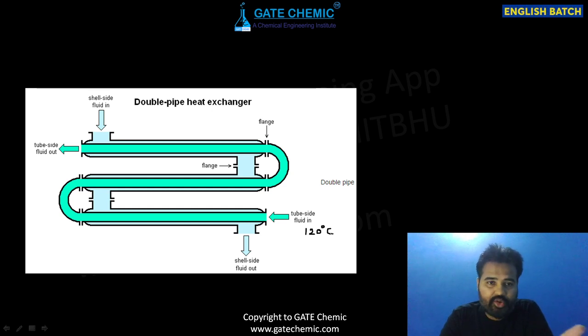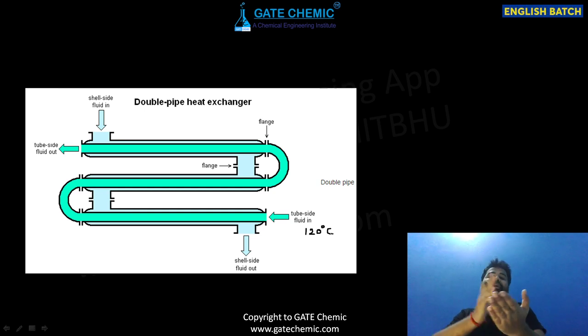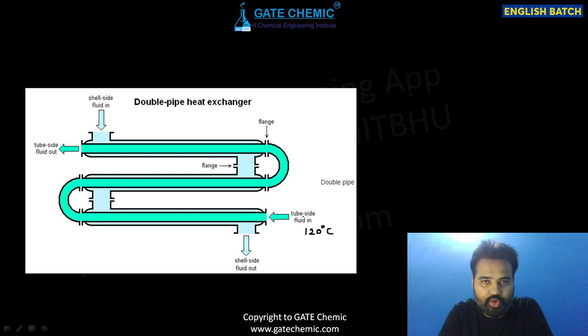But here, in this diagram, nothing is on the upper side or the bottom side. The heat exchanger is on the bottom, just on a horizontal surface. So here I am giving this. If it is vertical, then try to give 120 degrees Celsius fluid from the top towards the bottom, so that a natural circulation pattern will be there. Density will help your flow.